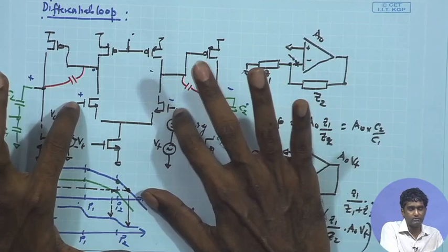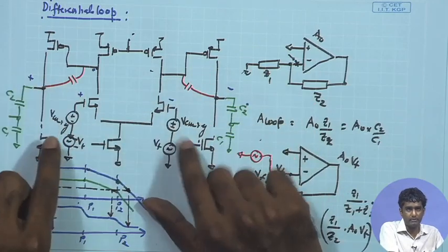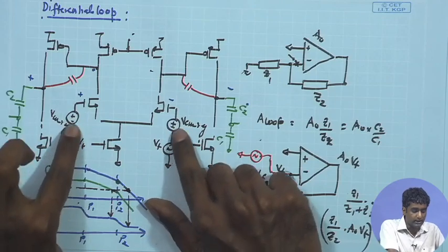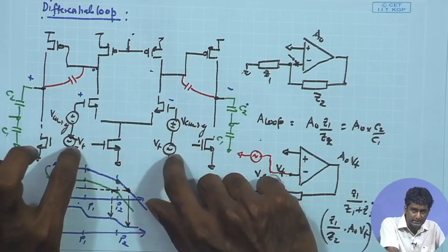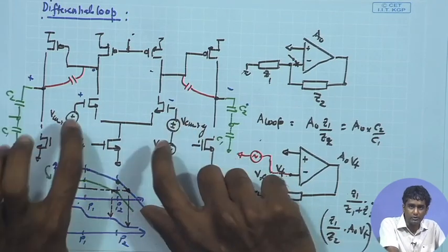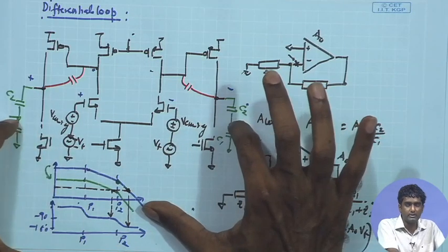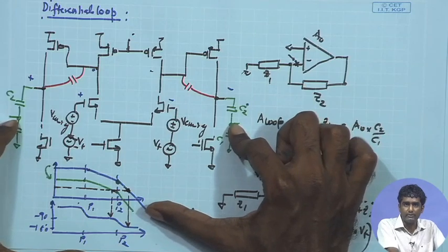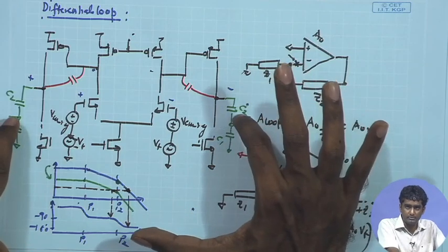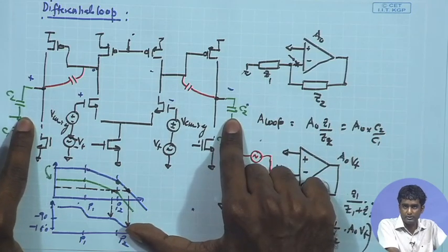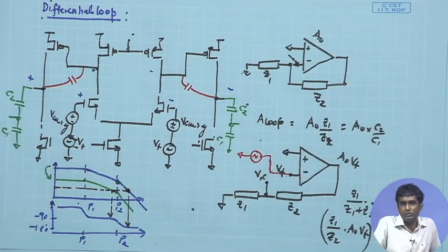So, to be accurate, you can always keep the RF over here, but even in that case you need to make sure that you are using a single source over here with a DC level equal to VCM ref, and then on top of that you are applying the AC signal VT for testing, and then you are obtaining the output signal over here. The phase response will be given by the gain from this point to the final output at the division of this capacitor. So, this is how you will be looking at the phase response for the differential